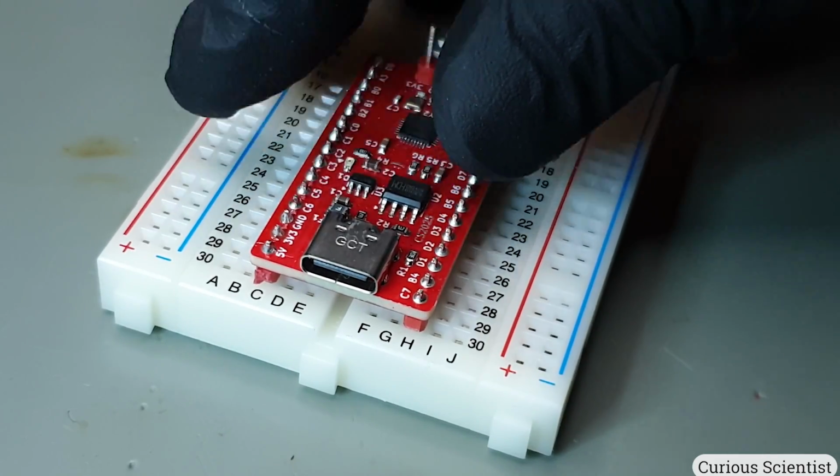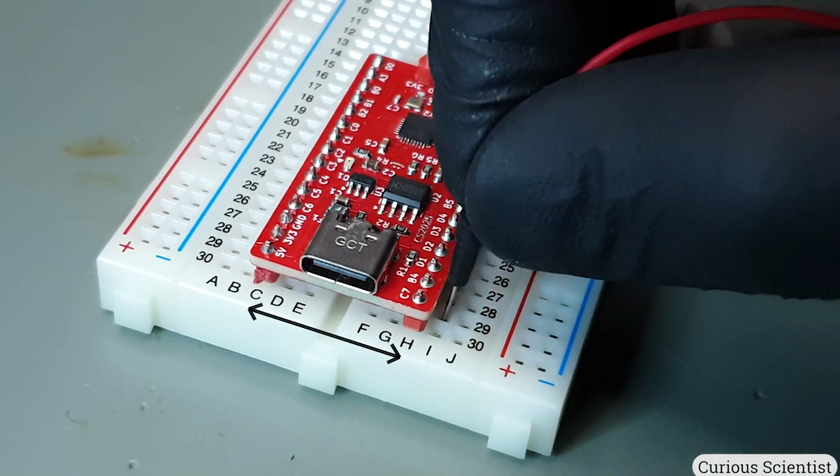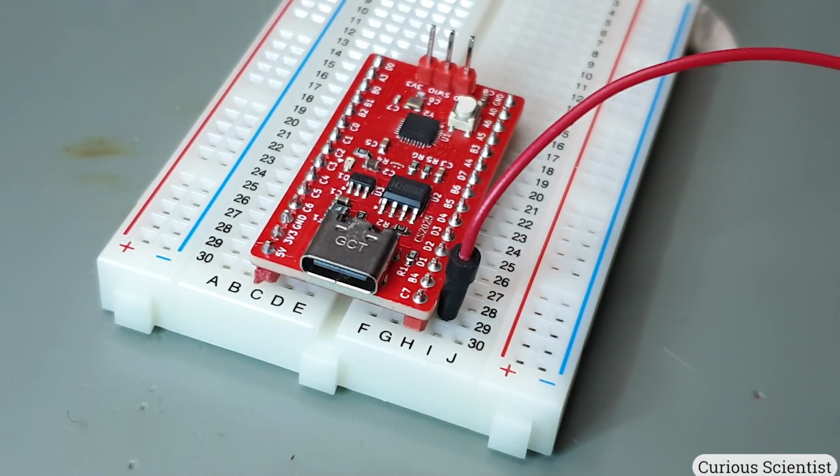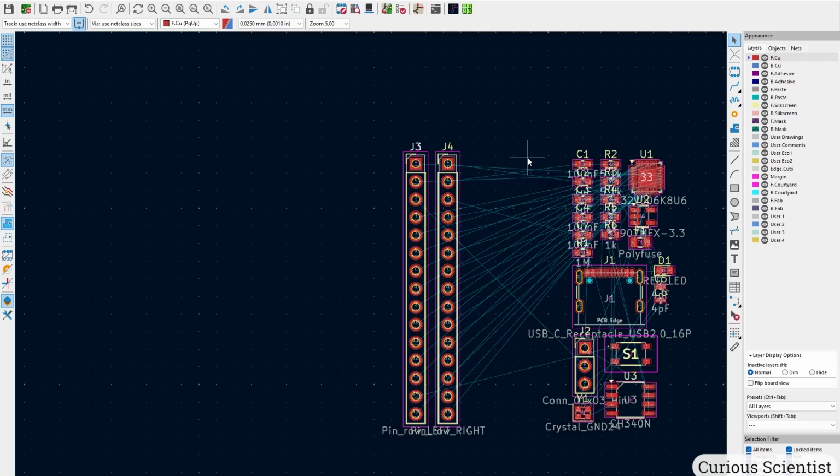So my goal here is to make the microcontroller board narrow enough so I can plug it in a breadboard. And for example, if I make it 8 pins wide, so 8 of these slots wide, then I will have still two rows of pins available next to the microcontroller inside the breadboard. And how to align that is kind of very easy.